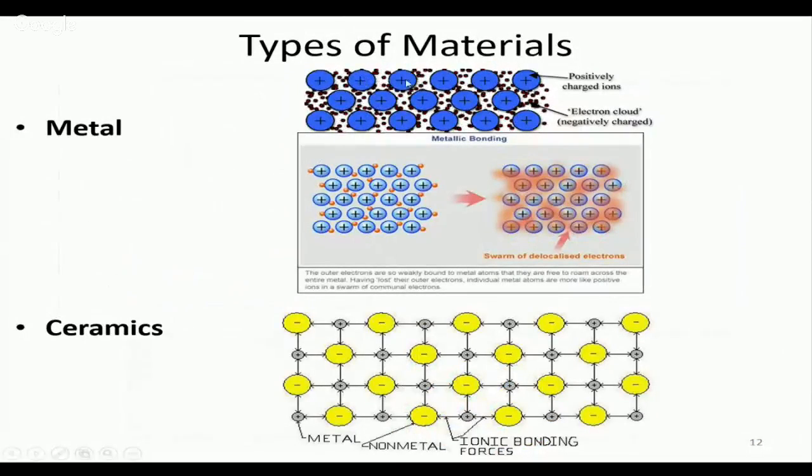in case of metals, we can see that all layers are of the same material, same atoms, if it is a monolith. And in case of ceramics, you have the alternate structure. So in any material you may have the notch, but under stress, this notch may be rounded or may not be rounded. In case of metals, there is a possibility of slippage.